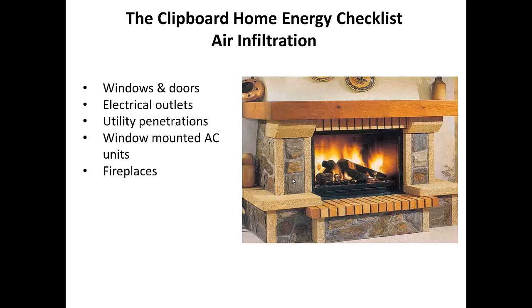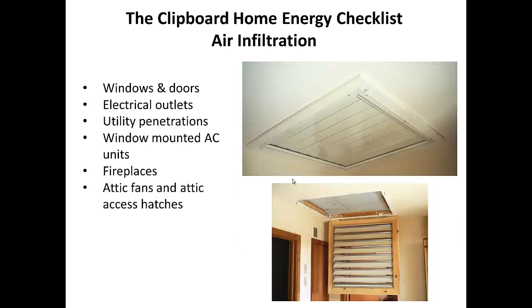You would be having conduction losses through that stone, because stone is a lousy insulator. So when that stone, if it's on the outside, gets cold, it's going to pull the heat from the inside right out. So that's conduction losses, or the heat traveling through a material itself.